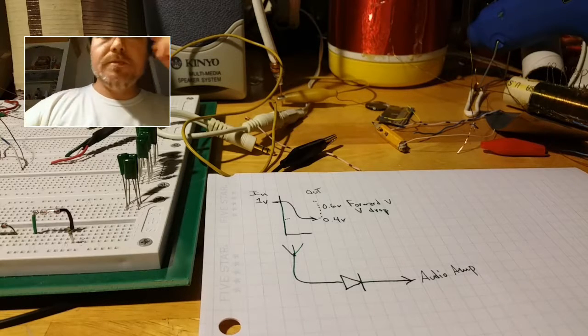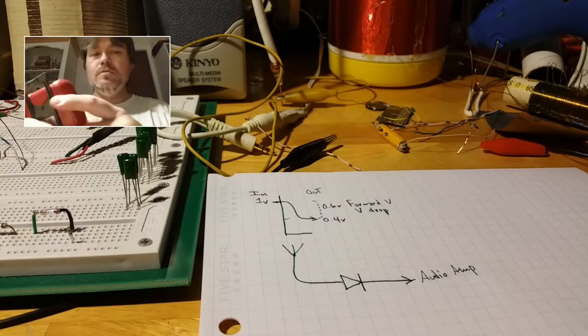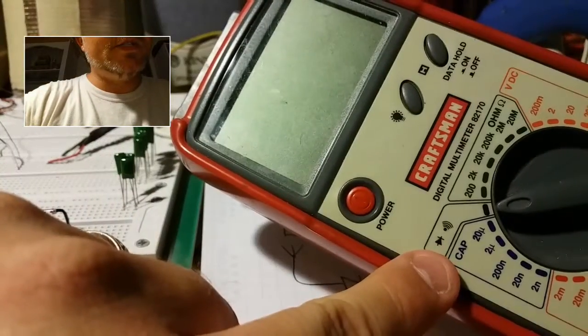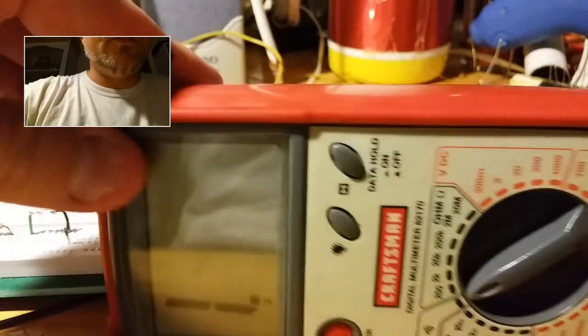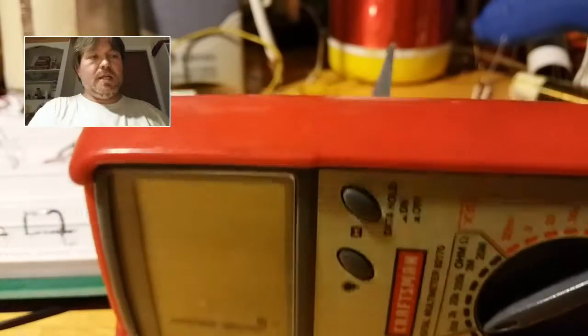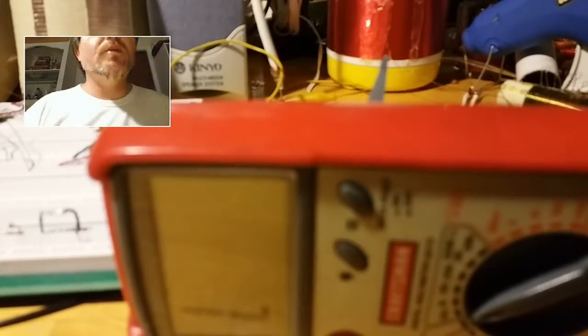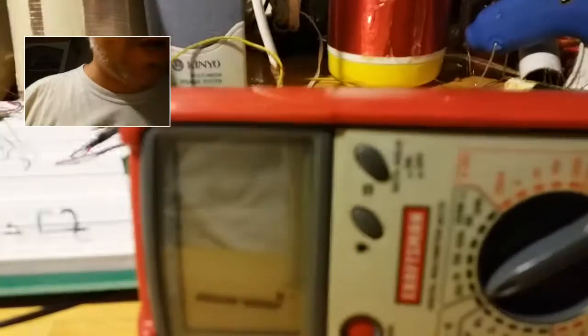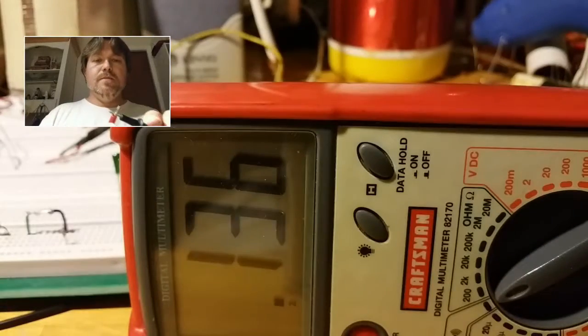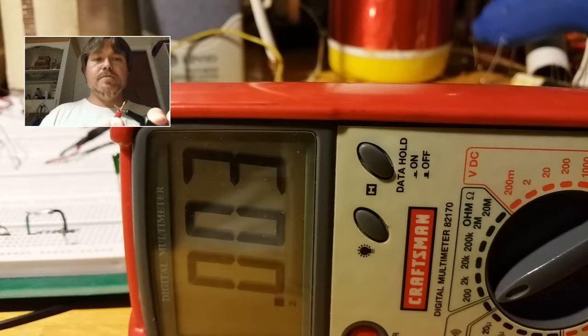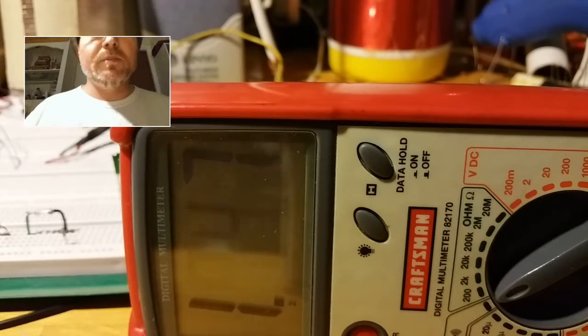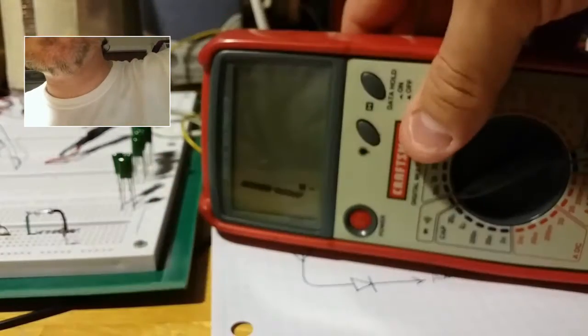Now, I have here a voltmeter that I've got set to the continuity and diode test mode. And if I take the leads to it, I don't know why it's being such a pest today. It was working fine earlier. You see, it's basically 0 volts. There's going to be a little bit due to corrosion on my leads, but it's essentially 0 volts.